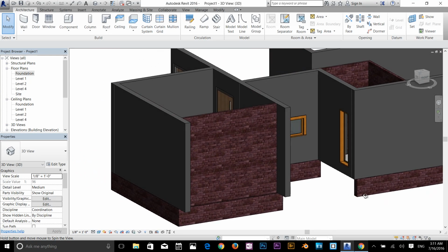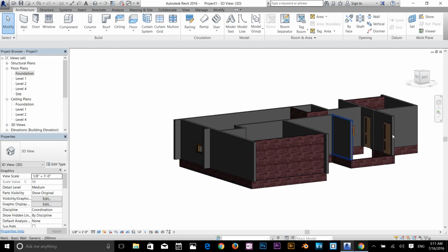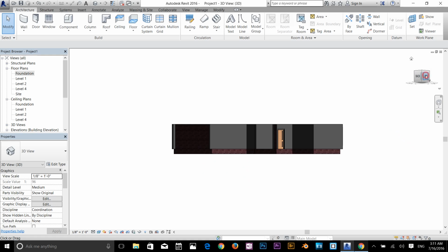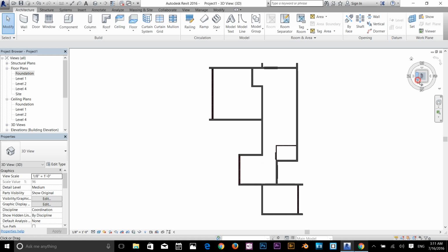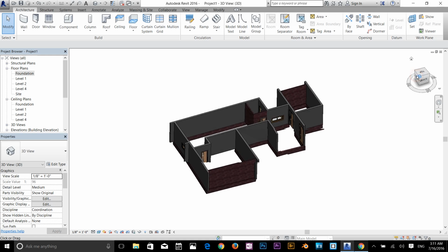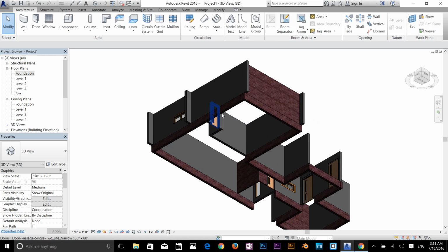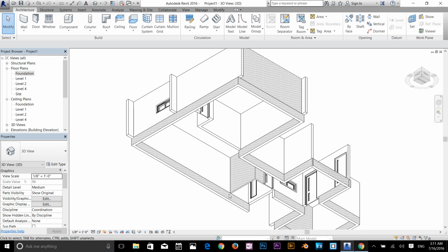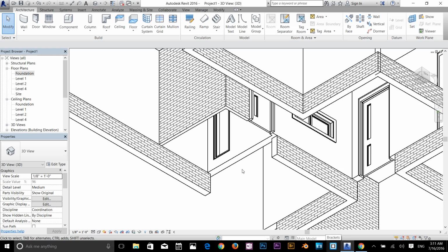Now we're gonna add some footing to our foundation, right? So let's go back, and I'm gonna show you how to use this wheel. This is basically a viewport. So if you click here, it's going to left, top, alright, and then the corner. All those views are available. It's very useful. So I'm going to click on this bottom back. So I'm going to zoom in, and let's change this to hidden lines so we can see the walls. Alright, so there is an error here.